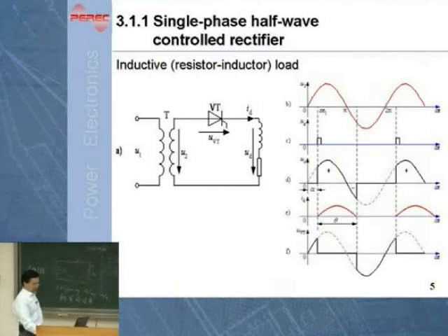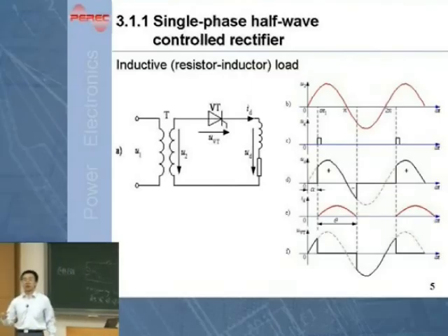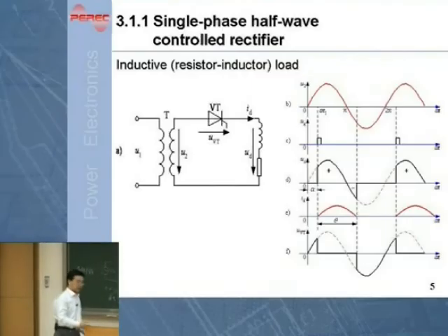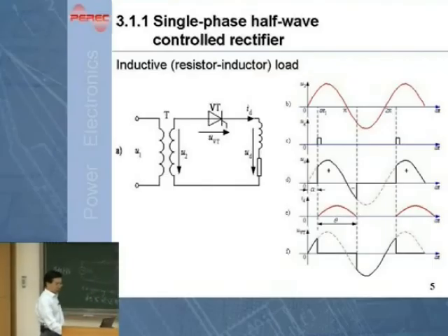When the input voltage is positive, I can control at what time to turn the thyristor on. This is the same as in the resistor load.